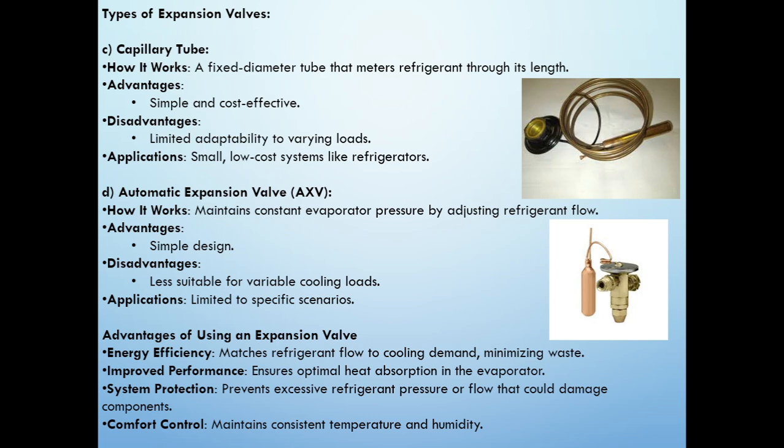The advantages of using an expansion valve: its energy efficiency matches refrigerant flow to cooling demand, minimizing waste. The improved performance ensures optimal heat absorption in the evaporator. System protection prevents excessive refrigerant pressure or flow that could damage components. And comfort control maintains consistent temperature and humidity.